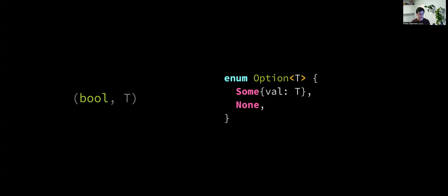Additionally, the compiler knows that this is an option type. The compiler knows that whatever bytes this T is when the tag isn't valid, it doesn't really matter because the user will never look at them. And so we can start doing compiler optimizations because we've given up control over whatever this value is in the clock cycles where it's not valid.